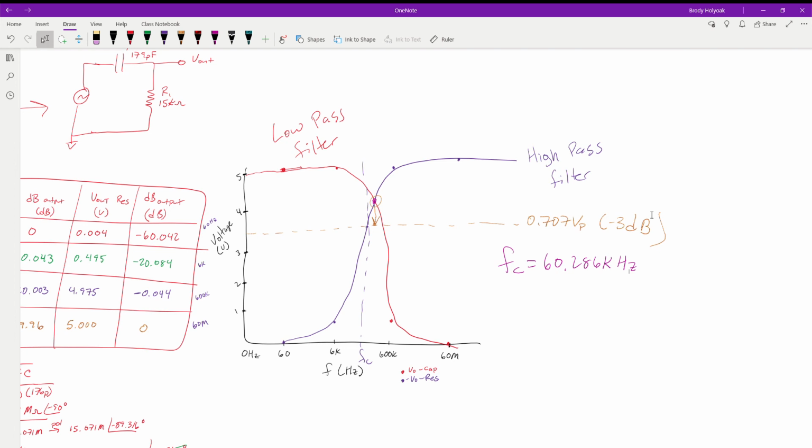And that's where the power of these filters comes in, is now we can calculate what is a high pass, what is a low pass, what's my frequency. Okay, what if I want to design a certain filter at a frequency because, for whatever reason, I'm trying to isolate that frequency? Maybe we're trying to isolate some noise that's coming in on our line and we want to track it down. So we're going to build a filter that's specifically designed to the frequency of the noise so we can start troubleshooting. Okay, do we have noise here? Nope, there's nothing there. Do we have noise here? Oh, there it is. So we know we can work backward through our system and trace this signal, eliminating everything else other than the signal that we're looking for. So that's kind of the real application and the power of filters.